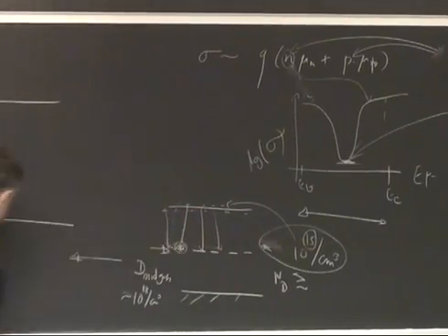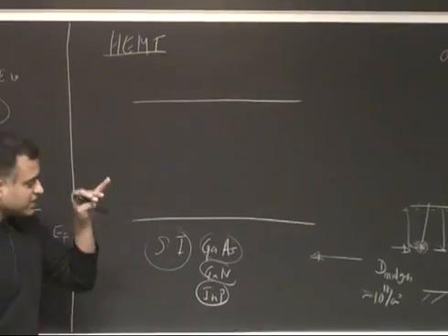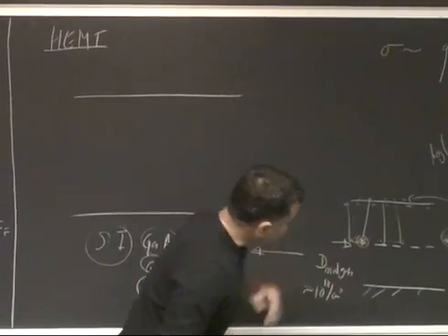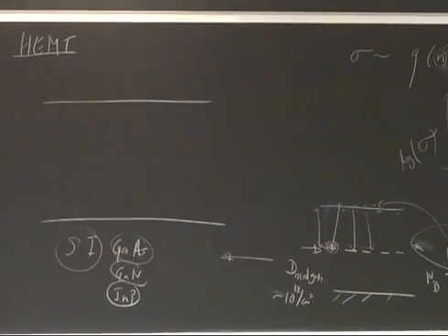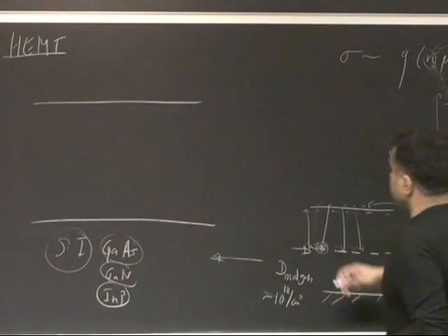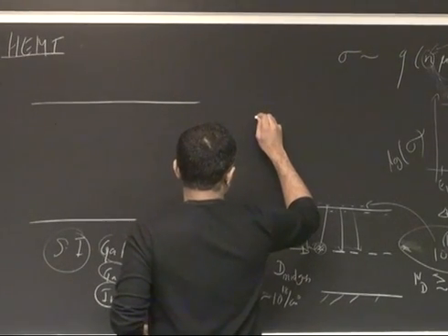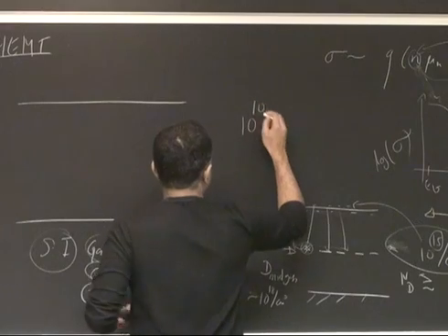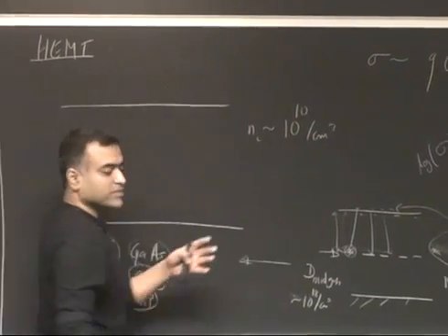So that is what is called a semi-insulating semiconductor, where you've intentionally put in deep levels to remove carriers and make it insulating. Now, the conductivity: if you look at silicon, the purest silicon possible has, remember, ni of 10^10 per cm^3, right?